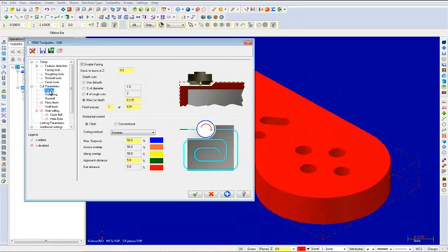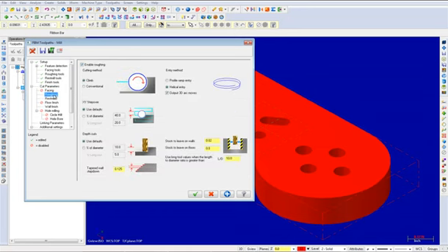We do not need to face the part. That being said, make sure that the facing is disabled. Next, select the roughing page. This page allows you to add roughing toolpaths to the FBM Mill operations and to define their cutting passes. Mastercam will create the roughing toolpaths before any rest mill or finish toolpaths. Change the XY step over and depth cuts to percentage of diameter. Now make the following changes as shown.